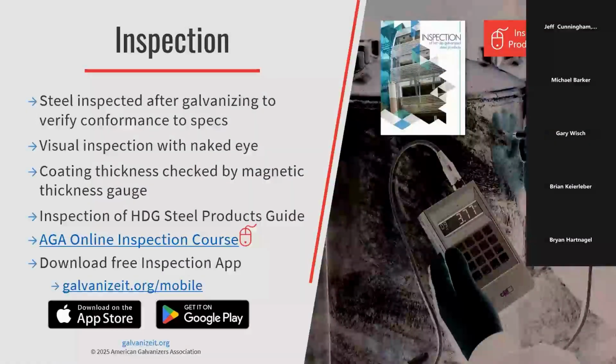All right, we get inspection of galvanized steel products questions all the time. So we have a wealth of information on inspection. All steel is always inspected to verify conformance with ASTM specifications, AASHTO, if you're working internationally, ISO, some other standardizing organizations out there. Typically, it's a visual inspection with the naked eye. Coating thickness can be checked by a magnetic thickness gauge.